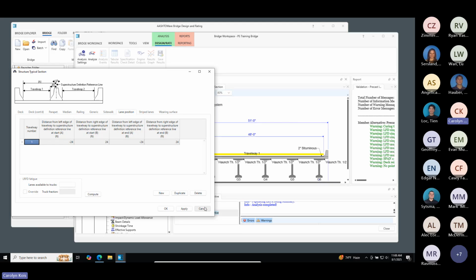The only thing to mention is that for the load rating itself, to get that rating factor, that comes back to the rating equation: capacity minus dead load minus all of those other loads, divided by live load. So if you model that pedestrian loading by creating an adjacent vehicle that's like a lane load, then that pedestrian loading is included in the rating equation along with the live load, if that makes sense.